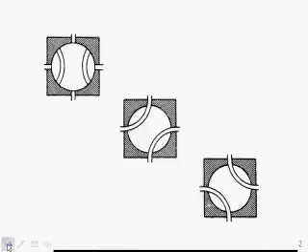Here's selector valves. This is one selector valve, and it shows it in 3 different positions. Let's say that we have hydraulic fluid, and we have pressure going in this direction, and this valve is shut. This is a piece of metal on the inside that can rotate. You've got an arm on here, and you can rotate it left and right. And right now the hydraulic fluid is blocked.